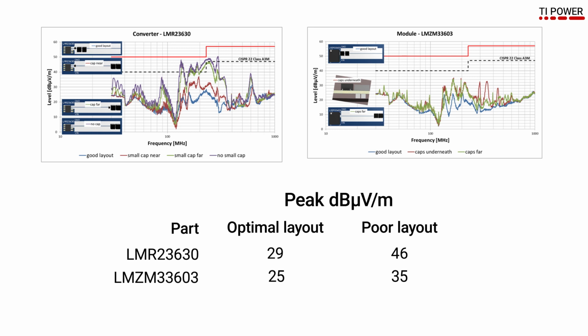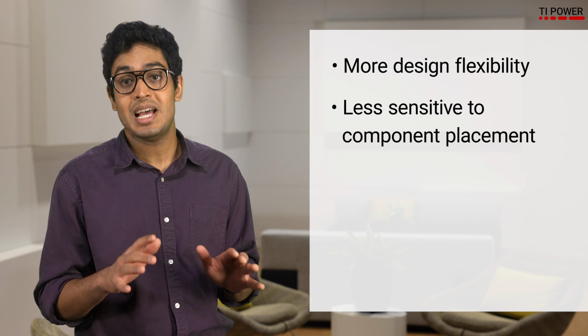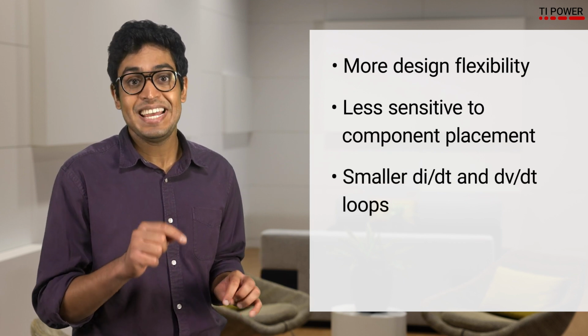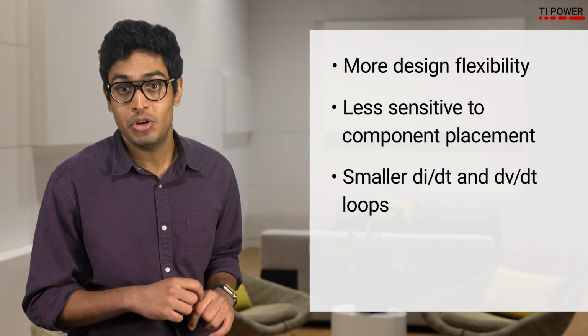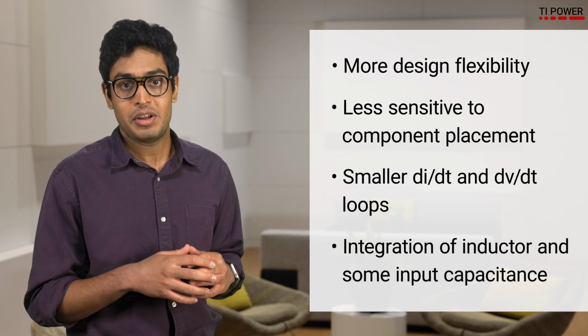Keeping the external capacitors close to the IC is still recommended, but as we can see, the power module is much more forgiving in the scenario where close placement of capacitors is not possible. Ultimately, this means more design flexibility as the module-based design is much less sensitive to component placement. This is all a result of the smaller di/dt and dv/dt loops that come with the integration of the inductor and some of the input capacitance.